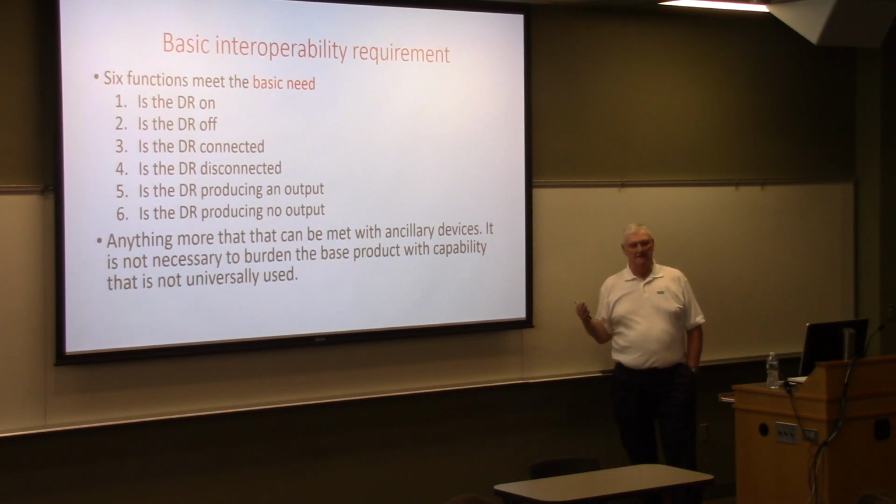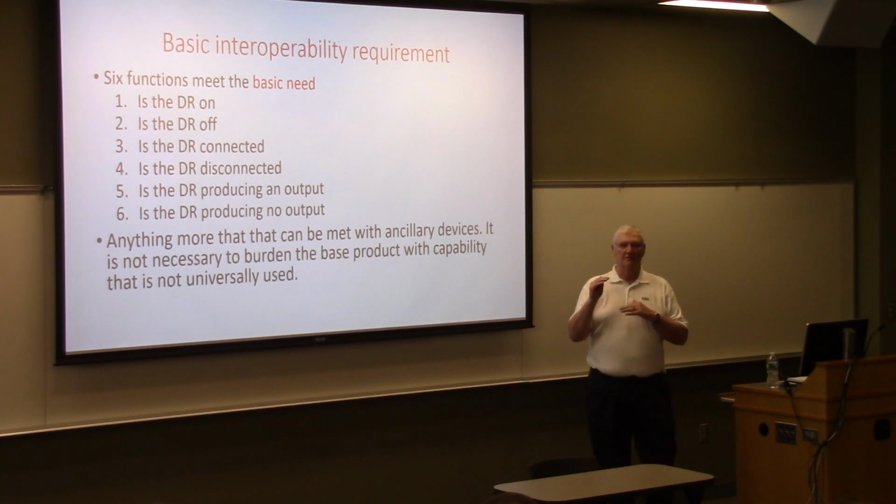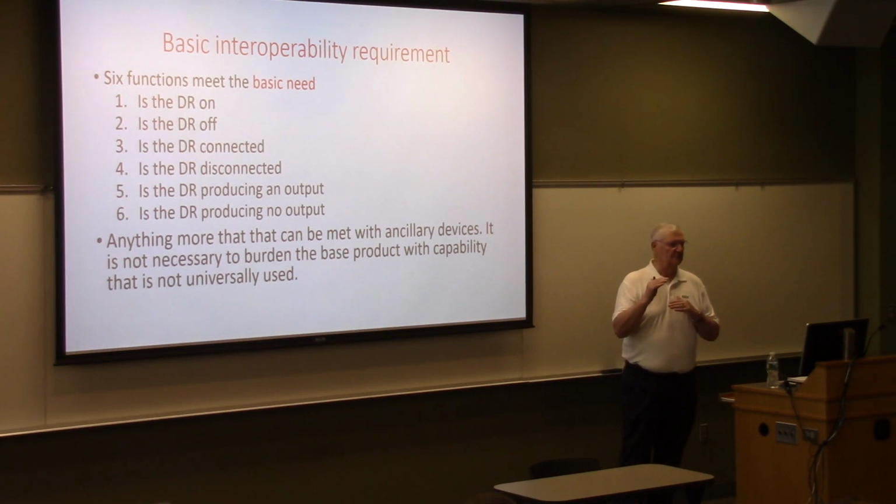The next thing is, and this gets hairy, I want the distributed energy resource to provide VAR support at its point in the distribution system. Well, how do you do that? Do I go out and tell it to switch to all VARs, part VARs? Do I tell it to switch to some unity power factor, 0.9 or 0.8 power factor? Do I communicate that based on time of day, so at this time I want VARs? There are a number of different scenarios on how you are going to turn on and turn off VAR support at the point of connection in the distribution system. All that stuff's got to be figured out.